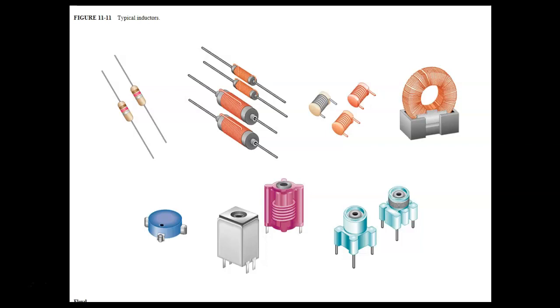So a basic power supply, basically, we'll start off with a transformer, and then we'll run into a rectifier, and that's going to be diodes, which you'd learn if you take solid state, which I don't teach. And then we'll go into a filter, which is usually just a nice big capacitor, so we know how that works now, right? And then we might use it that way. Normally after that, we'll run it into a regulator.